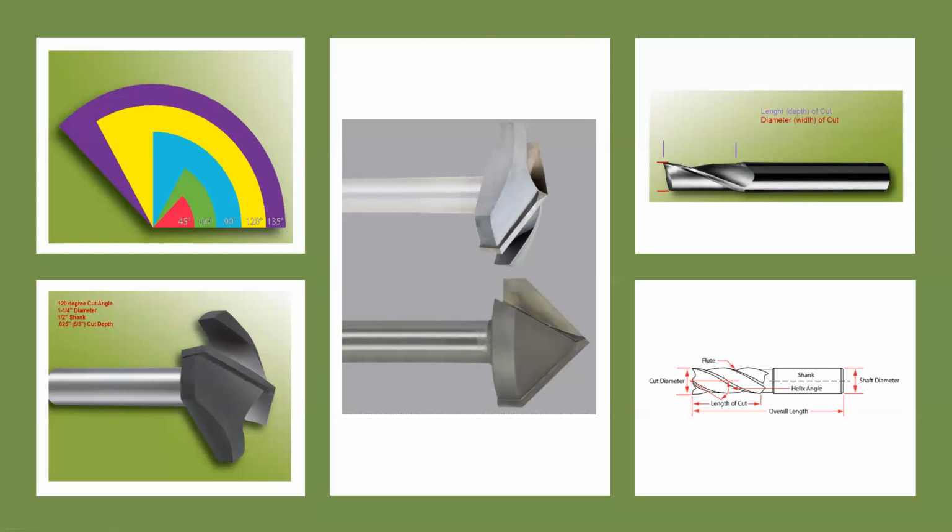And when we look at cutters and look at the different contours on the cutter, we'll go through adding a cutter or modifying a cutter into the tool database, because many of the cutters that you use for this type of work and other machining tasks aren't standard engraving cutters. They're going to be specialty cutters that are aftermarket cutters, and they will not appear in your standard tool database and will need to be entered.